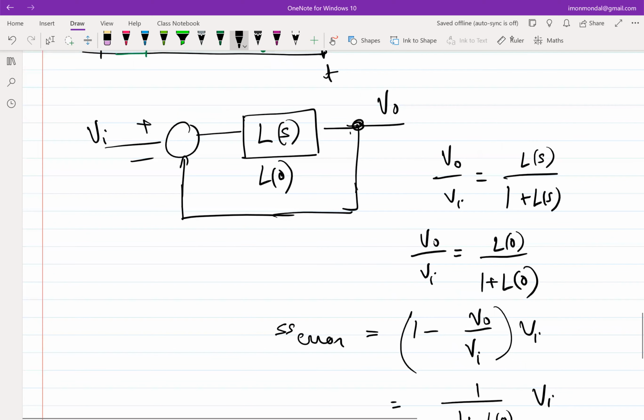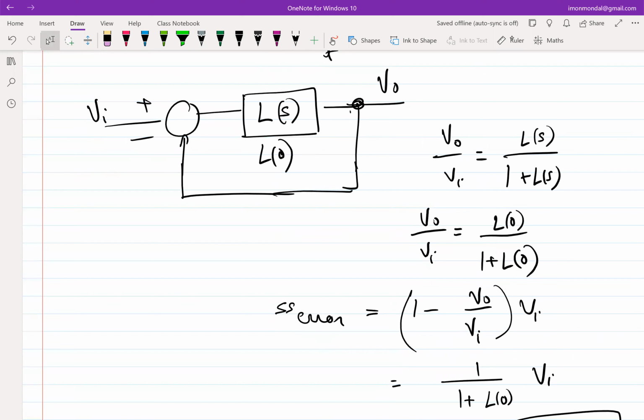Okay, so we are out of time almost. Any questions before we wrap up? In this non-ideal case, the error voltage is non-zero, and we have some finite output. So I was thinking that the integrator is taking some error voltage, but the output is stable. So can I think this way, that as the integrator is non-ideal, maybe there is some resistive part, so the capacitor is basically discharging, but to mitigate that, some error voltage is continuously rising?